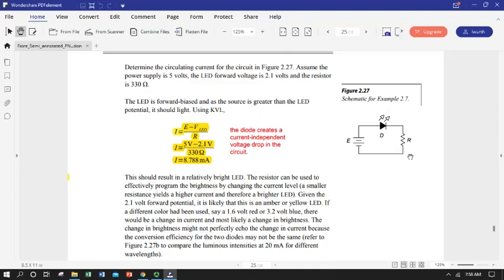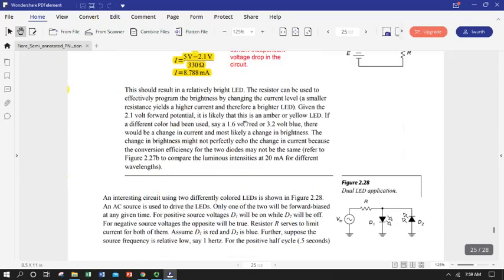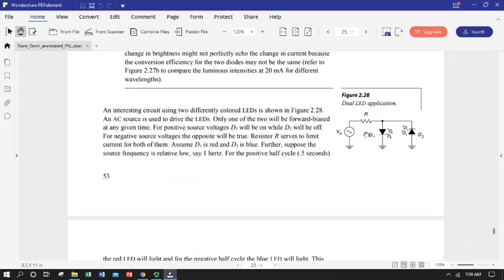So we're going to drop a voltage equal to E minus forward bias over the resistor, so we can apply Ohm's law to get current. So we've got 5 volts minus 2.1 volts divided by 330 ohms should give us current. Real simple, but a very different value for that forward bias voltage. Remember, typical silicon switching diodes, rectifying diodes will be 0.7. This is 3 times that much, again because some of our forward voltage is making some light for us, as well as just getting electrons and holes up and down the hill.